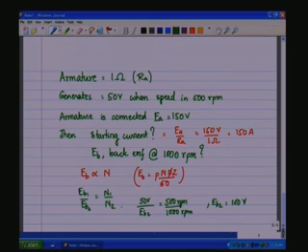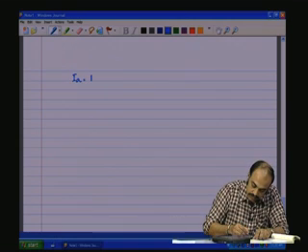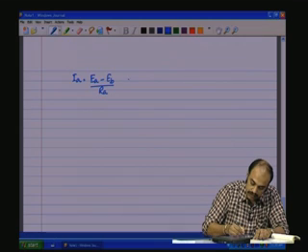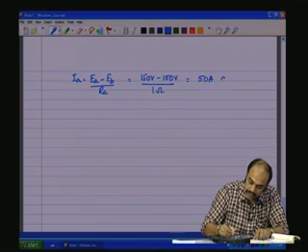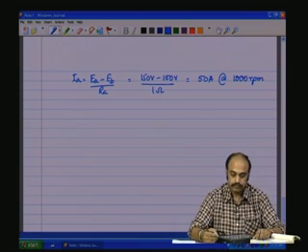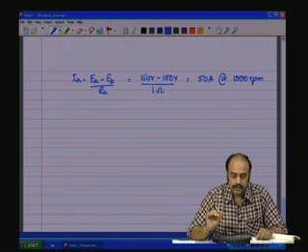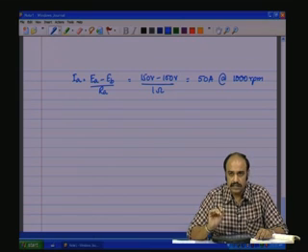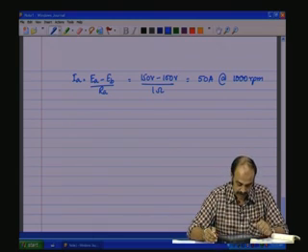So, now the back EMF at 1000 RPM will be 100 volts. Now, what will be the current in this situation when it is 1000 RPM? The current IA would be EA minus EB by RA, which is 150 volts minus 100 volts divided by 1 ohm, which is equal to 50 amps at 1000 RPM, isn't it? So, this is how one goes about calculating the armature currents, with special importance to be given to the starting currents, because a huge starting current means that the devices that are connected along with should also handle such high starting currents.